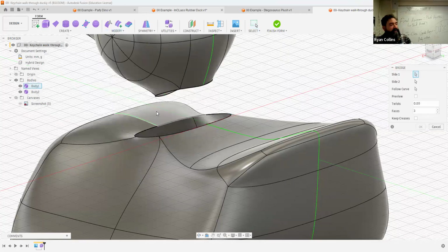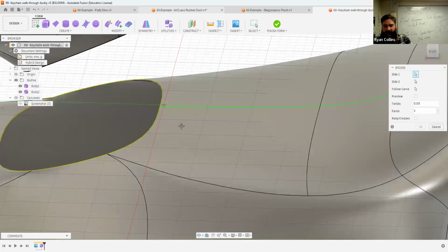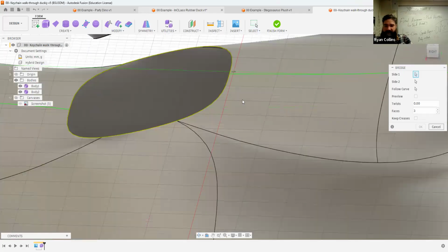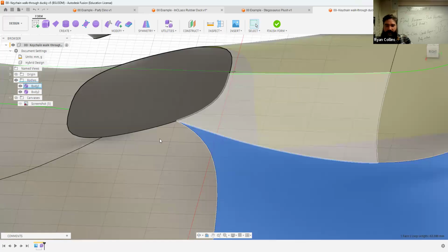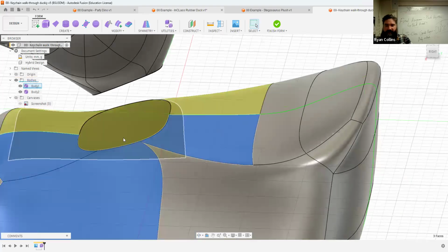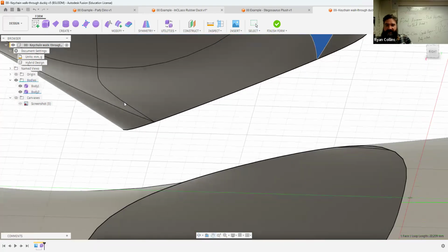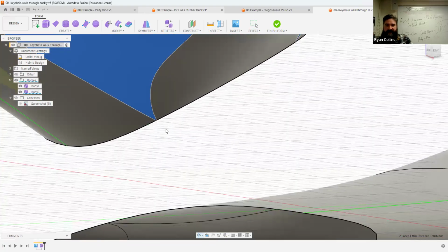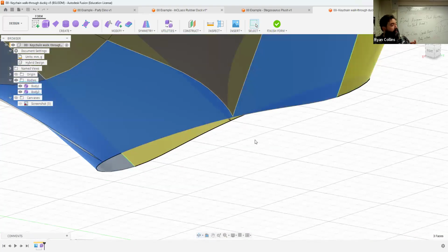But one of the main things is the number of faces has to match. So if I select that, like we did with the spoon, I can zoom in and double click, and that'll select all around. But if I'm looking at it from the side, let me cancel this so you can see what I'm talking about. Even though these meet in the corner, that one doesn't count. So 1, 2, 3, that counts. Up here on the head, same here. This face and this face, even though they touch the edge, they meet in a corner, and that doesn't count. So I have 1, 2, 3. 3 and 3, this will work, hopefully.